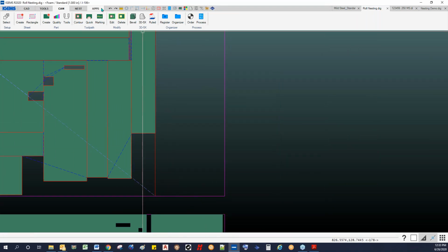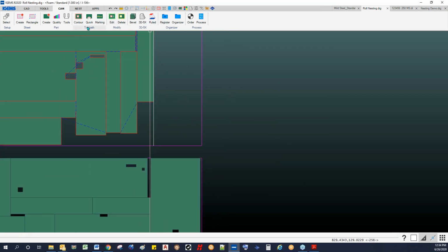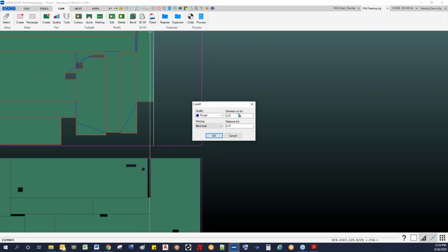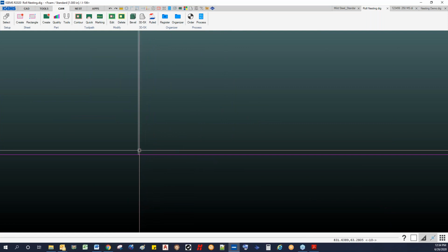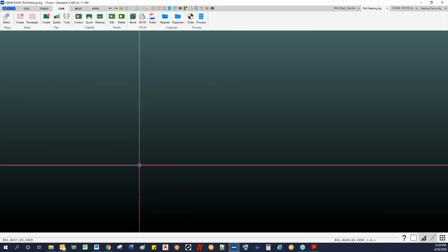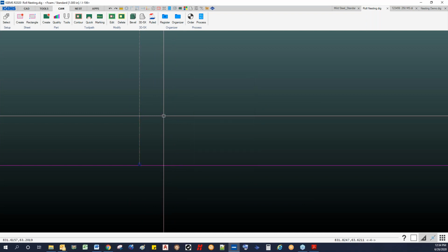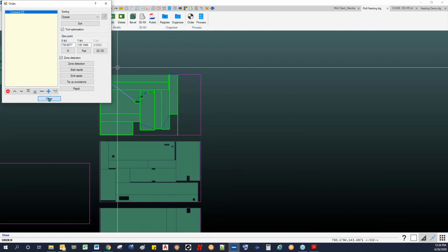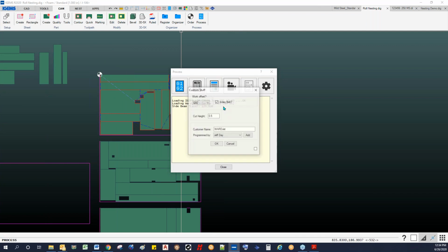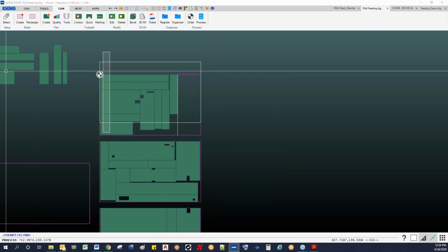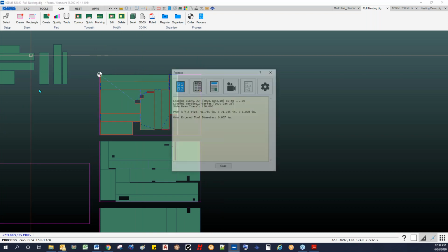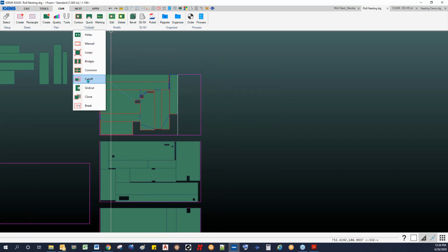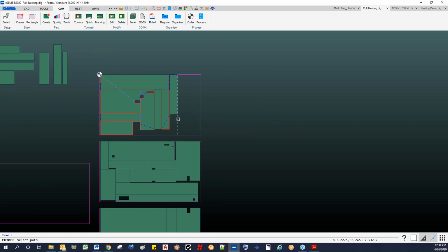So let me change that line here a little bit. And backspace, and let me add my cutoff again. And let's see, let me just move this point in a little bit. See if that's enough. Of course, I didn't add that to my cut sequence, so let me close that. So toolpath and cutoff, and okay, click on that. Set my 0 point.